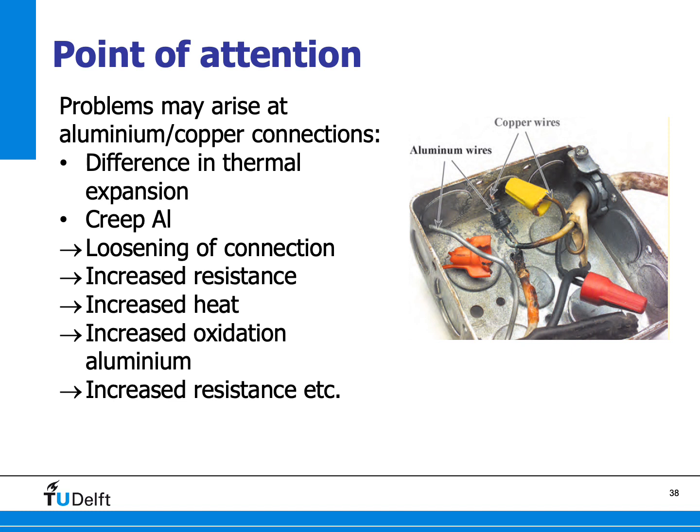The connection can loosen a bit. If that happens, then you get an increased resistance. That means the heat locally will increase. That will induce more oxidation of the aluminum, and because the aluminum oxide is a bad electrical conductor, you will have an increased resistance, and that will lead to more creation of heat, etc. And before you know it, you have a fire.